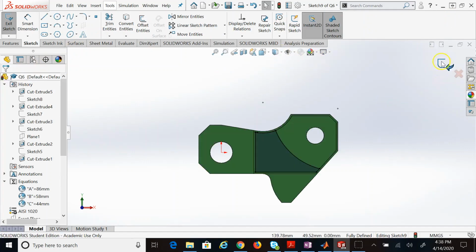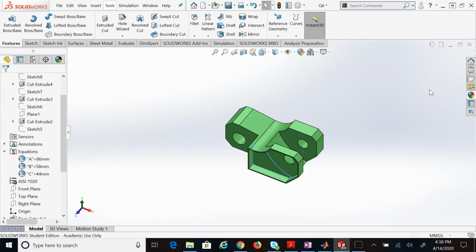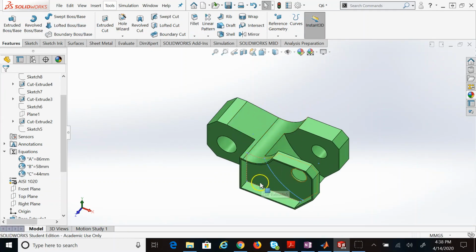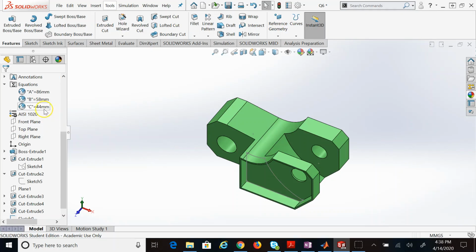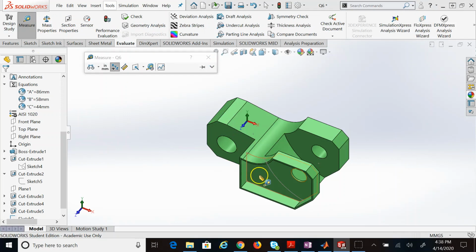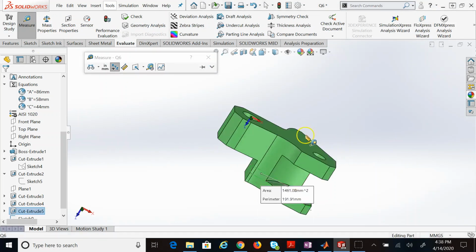And then I'm going to cut this guy in until 12 units left. Now remember, we cut in 7, right? The whole width of the part is C units, which is 44, so 37 left. From here to the back, I can measure it if you want, right? I can always go ahead and measure the distance from here to here.